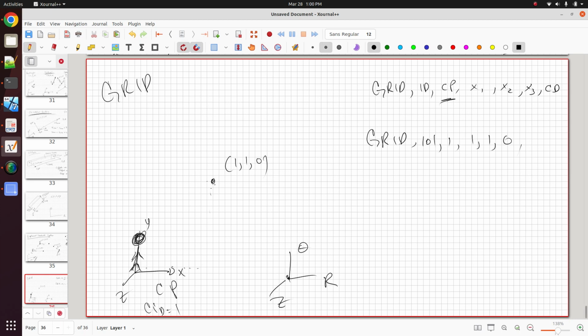So then you go through that procedure of drawing your r hat, your theta hat. So this is going to be your x and your y. And then you have to position your observer. Here I like to use the y-axis as the up direction for my observer. So here in the CD field, if this cylindrical coordinate system had ID 5, I will specify that CD is 5. So then what happens when you look at the displacements?